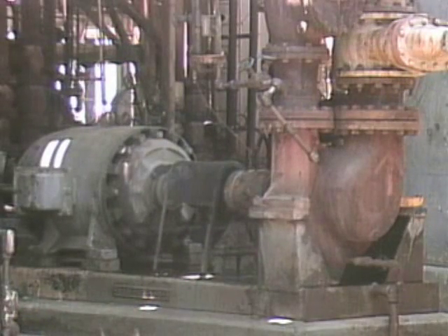Shell and tube reboilers use various fluids as heating media. For example, instead of steam, some systems use a hot fluid from another process, such as the hot product from a process reactor. As we've seen, a forced circulation reboiler system requires a pump to move liquid.